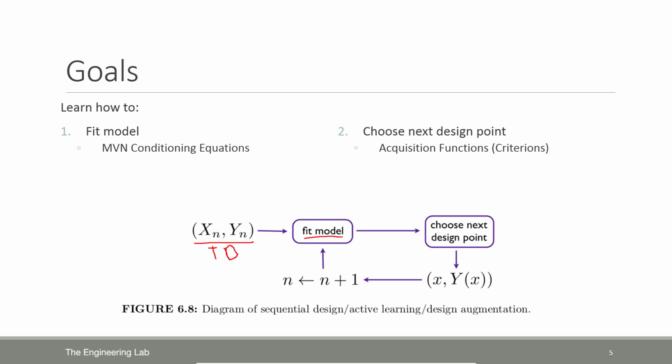The acquisition functions help us select a candidate point that might be a better design. Once we have this candidate point denoted by X, we plug it into Nastran, where Nastran could be seen as a black box function. We run Nastran again. After that, we get new output, and then we update the model again with this new output. And then we just repeat the process again and again.